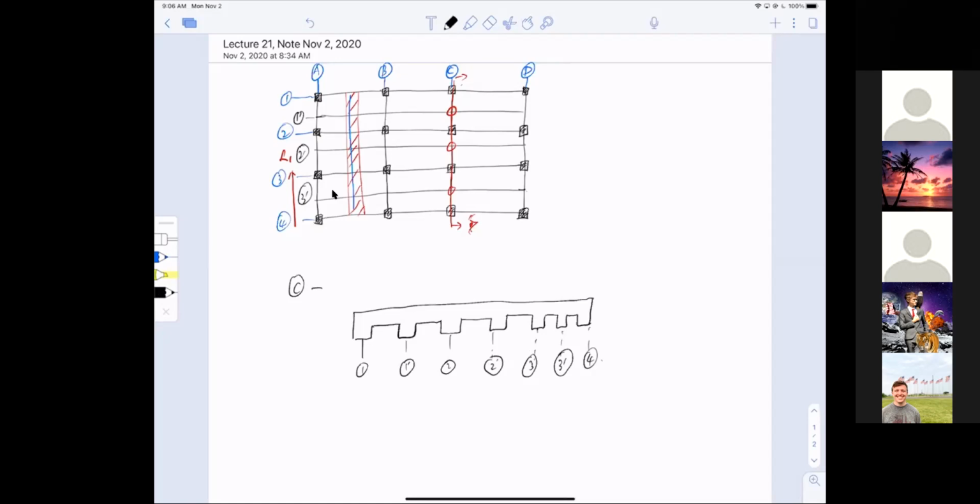So the span distance is Ln, so this is clear span length here, here, here, here, right? And corresponding to here, here, here, here. Okay, so when the homework is asking you whether you can apply the moment coefficient from ACI, this is where you're going to use the span length. These are the distances you use for span length.